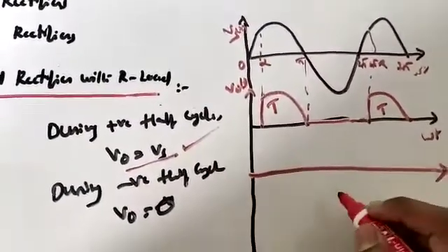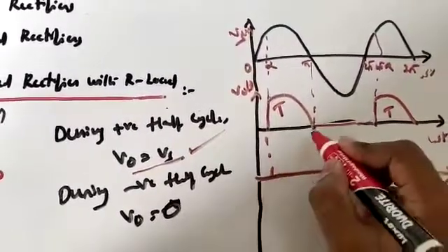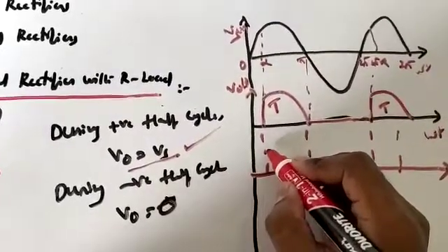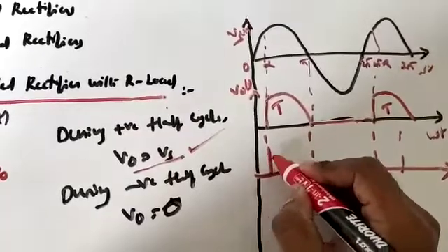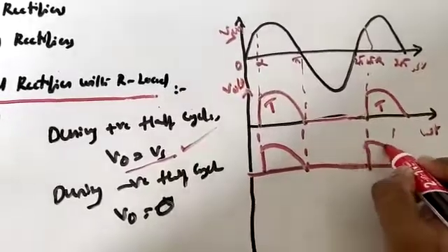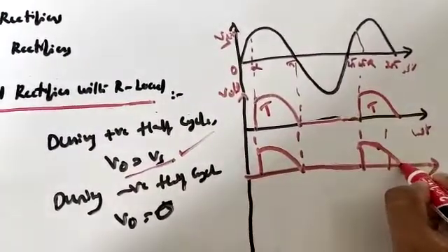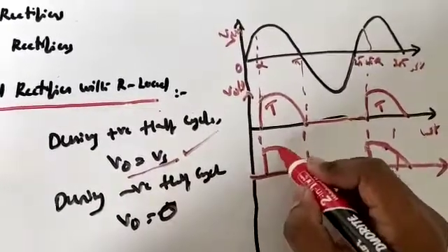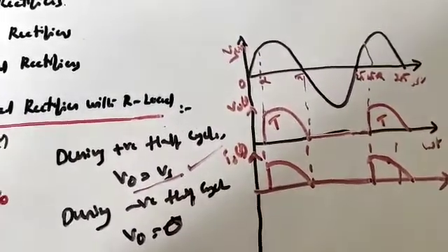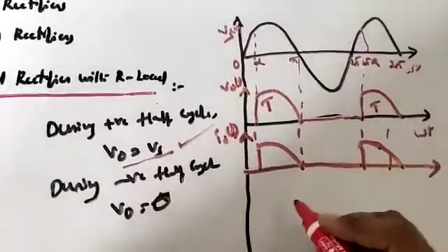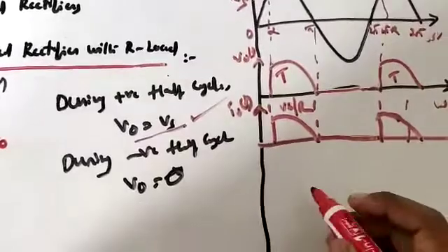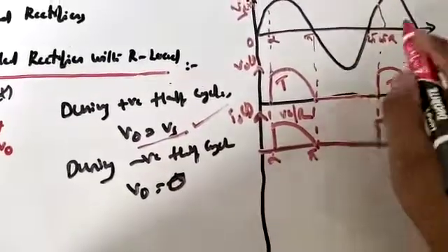Now if you consider one thing here, I told you in the previous class, in our live sessions, that both voltage and current will be in phase for a resistive load. So the current will be like this. This is the current value I0 of t. Please go through the PPT or slides which I am going to provide you when you watch this video, right? So I0 is nothing but V0 by R, right? Now this is alpha, this is pi. You try to mention all these things.